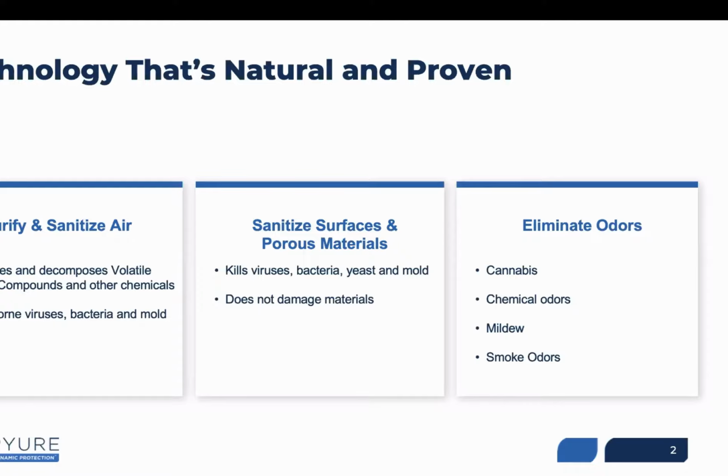They're going to be positioned in opposite corners, blowing in opposite directions to generate a bit of a cyclonic action within the grow facility. And that'll give us more exposure time and honestly a higher degree of air processing within the space before anything is actually discharged out of the greenhouse.